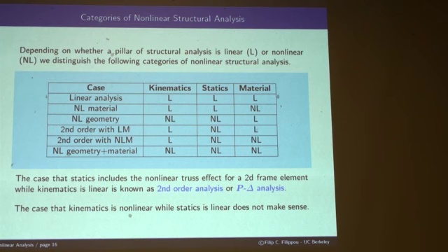So you assume that the axial forces are so much more dominant than everything else that they're the only ones that deserve to be studied in the deformed position. That particular branch of analysis is known as p-delta analysis or second order linear analysis, if it is associated with linear materials.